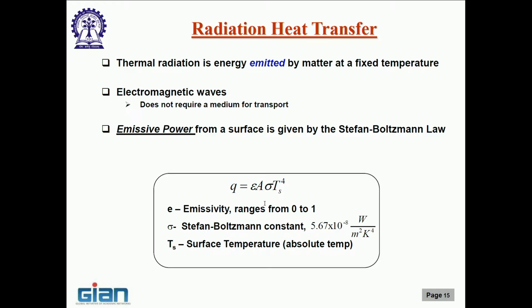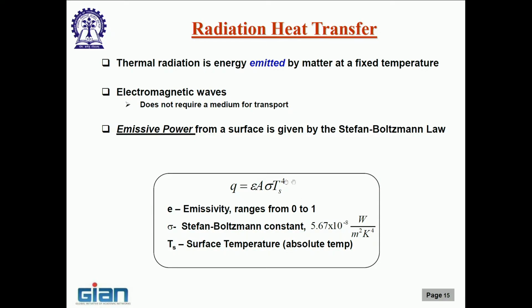It is difficult to come up with an exact definition of thermal resistance, but what you will see is that it is also a function of temperature, because the heat that is emitted and the heat that is absorbed is proportional to the fourth power of the temperature. That is the problem. You cannot just remove delta T and equate it as a potential difference for an equivalent electrical circuit. All right. So, this is the emissive power that is given by the Stefan-Boltzmann law.